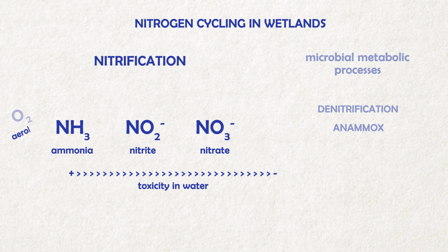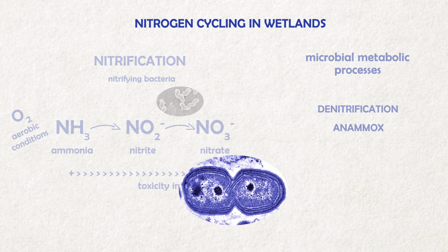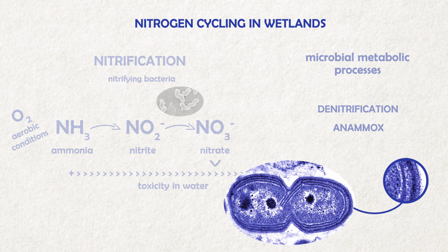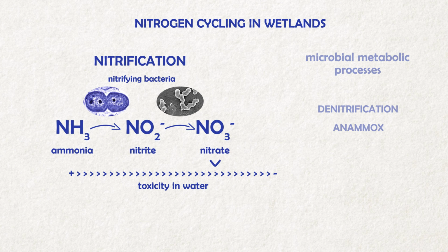Nitrification is the oxidation of ammonia to nitrate, a two-step aerobic process in which some species, like the bacteria Nitrosomonas, oxidize ammonia to nitrite. And then other species like Nitrospira oxidize nitrite to nitrate. Many species of nitrifying bacteria have internal membrane stacks, where key enzymes in nitrification are located. Nitrifying bacteria are important in wastewater treatment, removing ammonia and releasing less toxic nitrogen compounds.